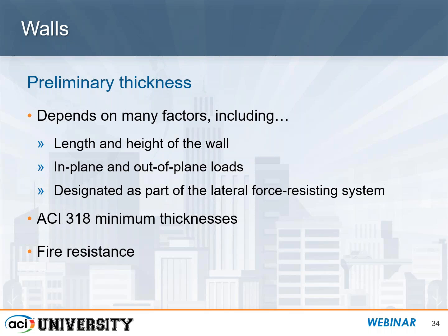and then determine how much longitudinal reinforcement you need in the wall. There are some minimum thicknesses that are given in ACI 318, but those are basically for walls that are designed by the simplified methods to utilize those equations in the code. That's because of the limitations of those methods. Then there's some minimum thickness that are prescribed.